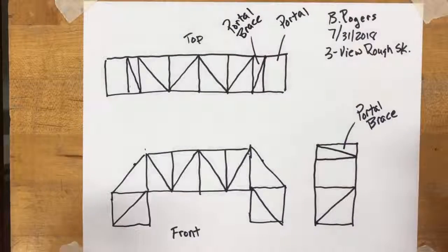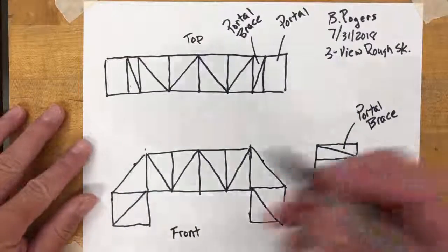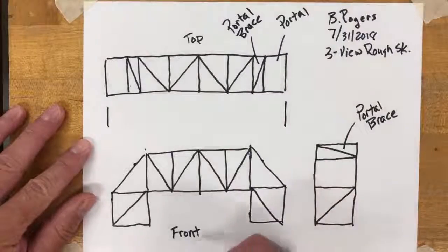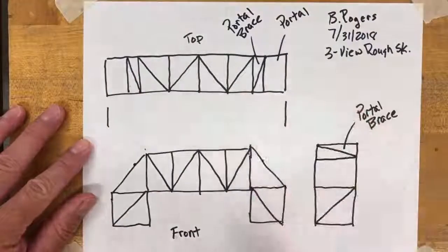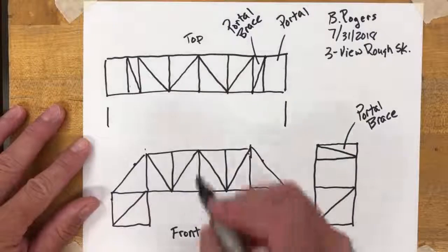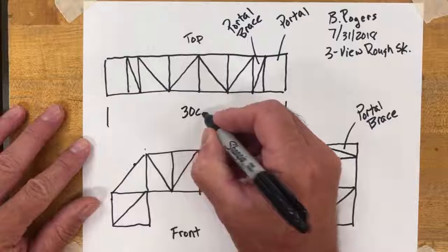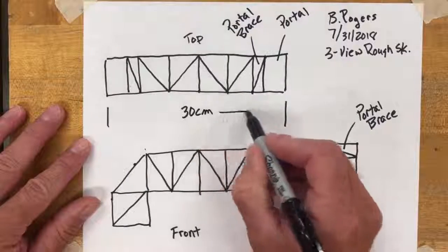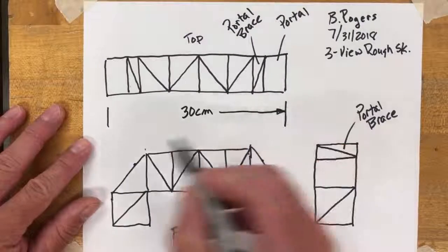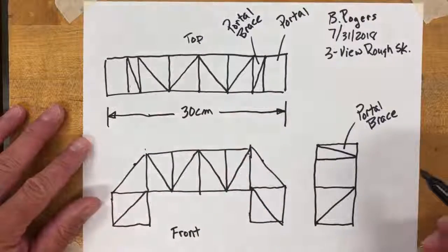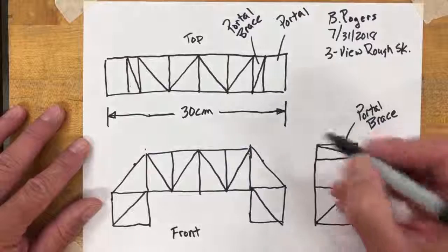Okay, at this point here, the drawing is mainly finished. We just have to assign some dimensions to this here. We're going to use some extension and dimension lines. So there's a couple extension lines that extend off the corners of the object where I want to measure from and to. And then I'm going to put in the actual measurement that I desire here, and that's going to be measured in centimeters according to our bridge specifications. So it's 30 cm. And so you can see I'm putting in some dimension lines here with arrowheads in there. And I'm going to do the same here for the height.